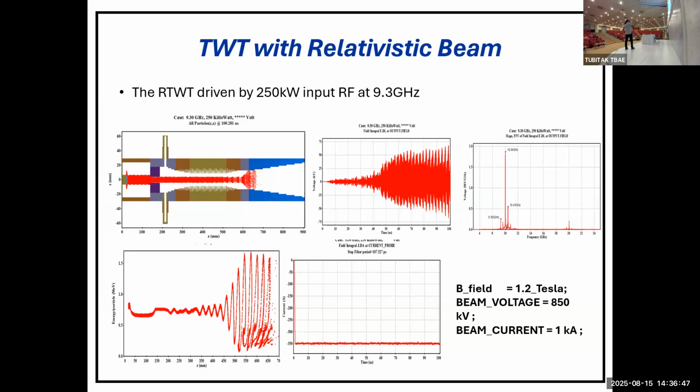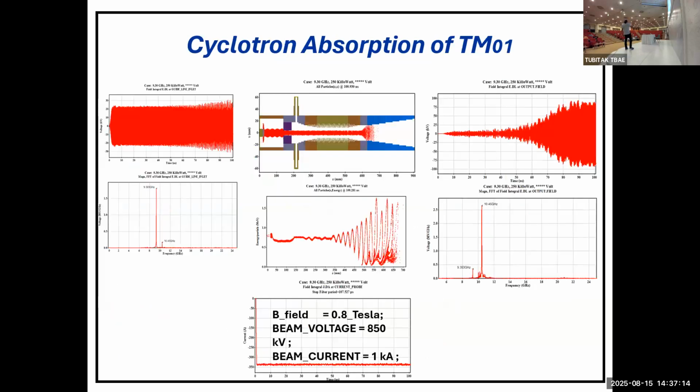Now this is the study for the whole structure, and we are injecting the beam, and we study the input coupling, how it's changed, and what's going to happen at the output. You see here, there is mode competition. Whenever you see this, there is mode competition, and the problem is that your amplifier is working as an oscillator as well. We have both, and that took a year from students, optimizing things, changing.